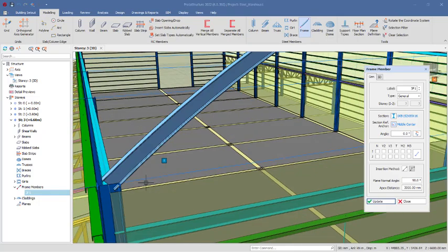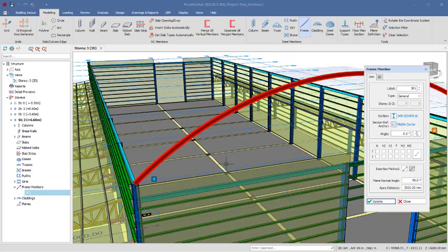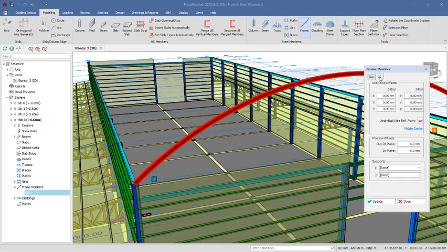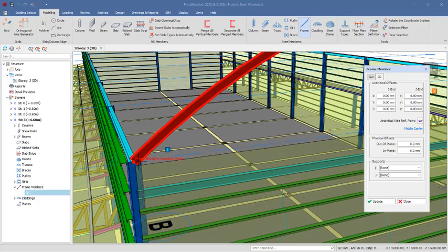Having placed this, you can also come to the 3D options, and these 3D options will help you to have a physical offset of out of plane and in plane. All right, outside the plane and in plane. And so you can also have analytical offset of the I end and the J end. So you can do that successfully. Maybe you want it to go down, you can also carry out that using this provision successfully.